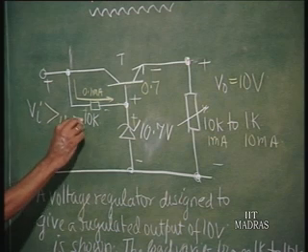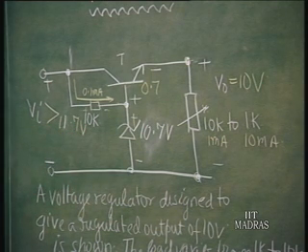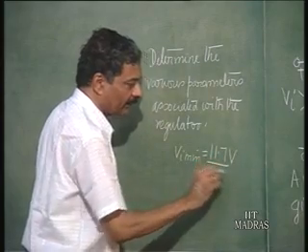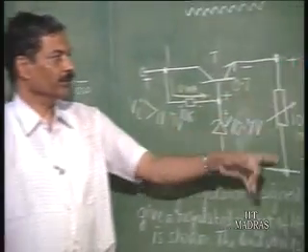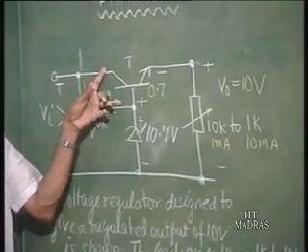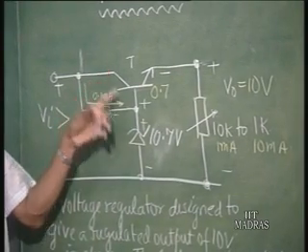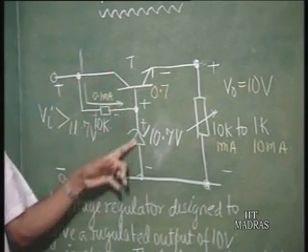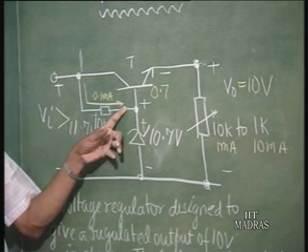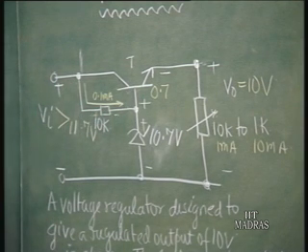So, the current is going to be greater than 0.1 milliamperes. So, if that is the case, we get V I minimum as equal to 11.7. Look at it from another point of view. This is 10 volts, this is 0.7. As far as the transistor is concerned, this can go down to 10.7, no problem. So, the minimum is always fixed by this, in this case the zener plus whatever minimum current is required here, is going to fix up the minimum.